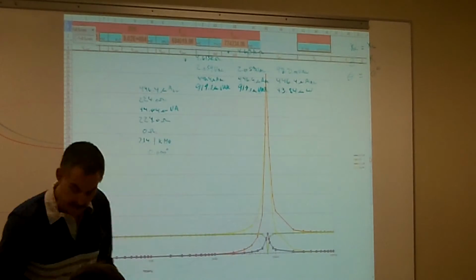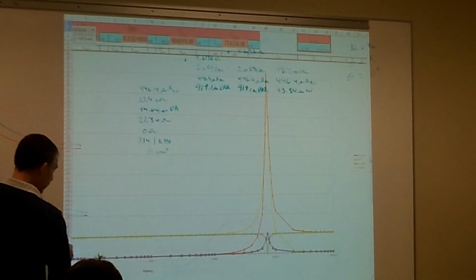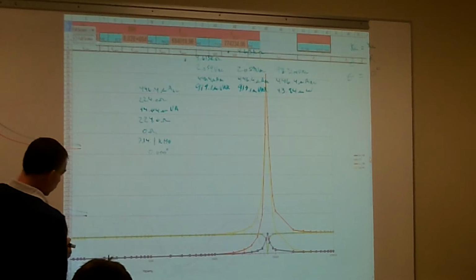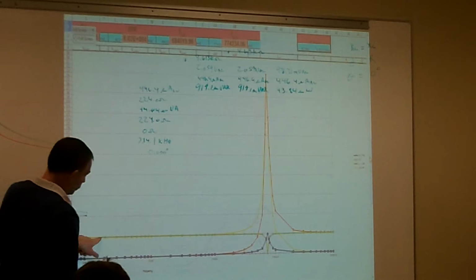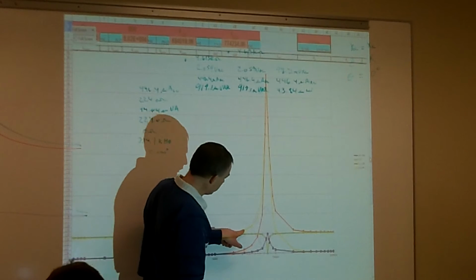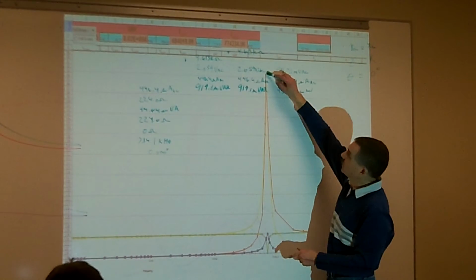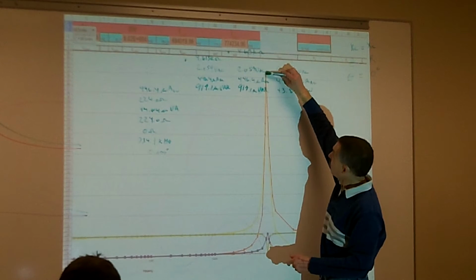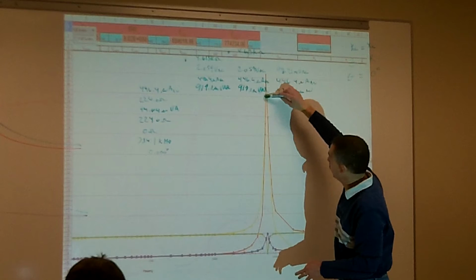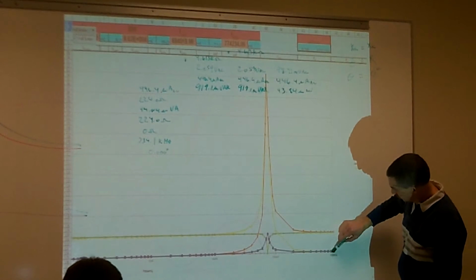So when we're starting out at a very low frequency, and this is what I was trying to draw up but couldn't quite get, my yellow is my voltage of my capacitor. It's going to start out at approximately my source voltage. It's going to go up, and then when I get close to my resonating frequency, it's going to shoot way up. It's going to induce a larger voltage at this point. And then as I keep on increasing my frequency, my voltage of my capacitor ends up going down to 0.